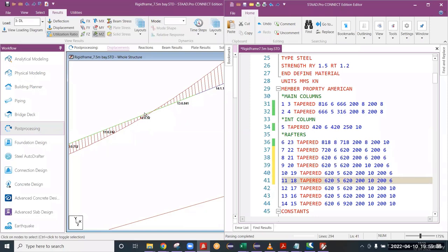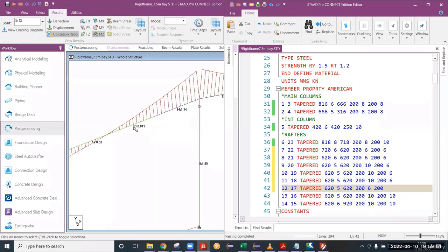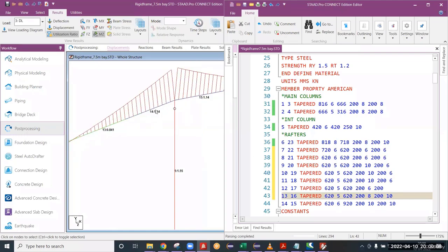12. In the 12, the bending moment is changing. Contraflexure. So you can change all the thicknesses here, no problem at all. And if you observe 13, the bending moment is top. To counter the bending moment, the section at the bottom should be strong. So you can reduce the top here. You can reduce it to 8. And if you observe, yes, this is the critical one.